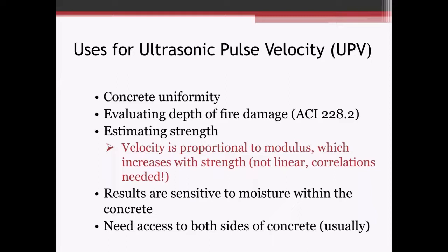Results are sensitive to moisture within the concrete. That's something the user or operator needs to understand, and it's certainly important in early age concrete, when the concrete may be a little more green, 1 day, 2 days, 3 days old. It's certainly a factor with cross-hole sonic logging, and we're usually doing CSL testing within 3 days or so after the concrete was placed. But it's all uniform. All that concrete is the same age, with the same relative moisture content. So we are comparing apples to apples within that drilled shaft.